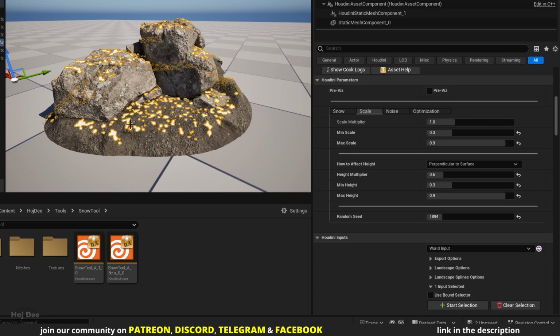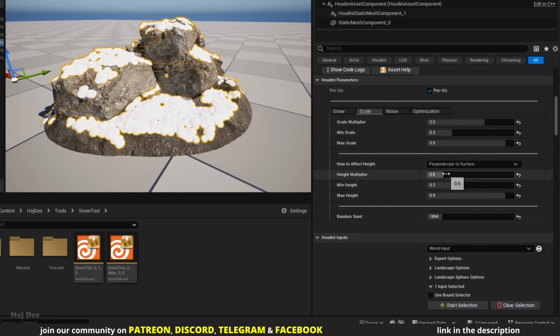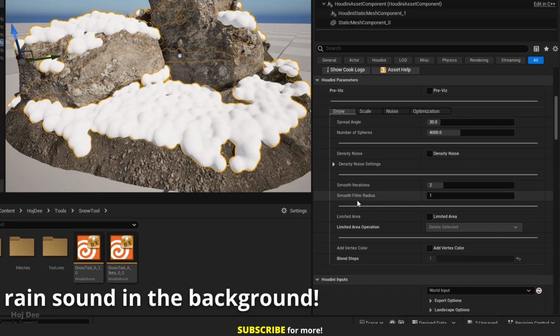In this case, I want more snow, so let's enable it and tweak the scale parameters. Let's set the scale multiplier to 2 and the height multiplier to 1.5. And let's disable the previous option to see how the snow looks now. This looks better now. Under the snow tab, let's also increase the smooth filter radius to 2.